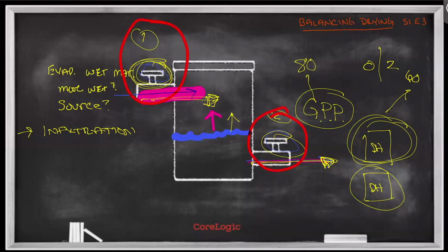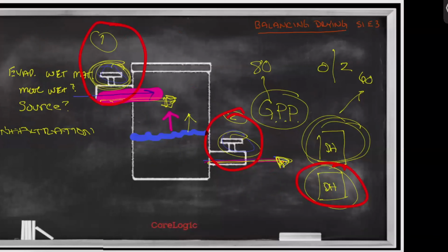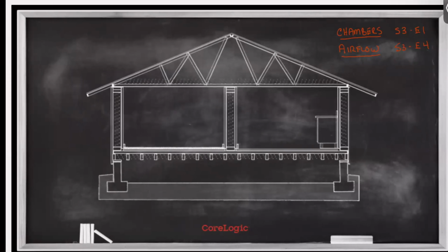All right. And is there a factor here that I didn't consider or something that I need to address other than just adding another dehumidifier? Now, at the end of the day, if adding additional dehumidification is what we're left with, then so be it. So humidity control analysis, all right, and that's what this analogy is for us, and really understanding that humidity control is two sides. It's the rate at which humidity is being added to the air and the rate at which humidity is being removed from the air.